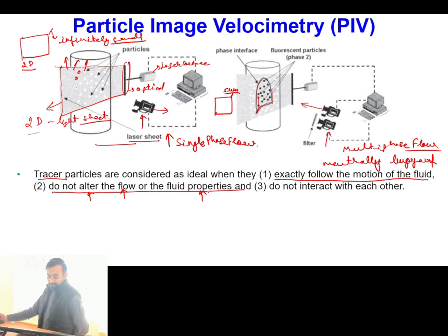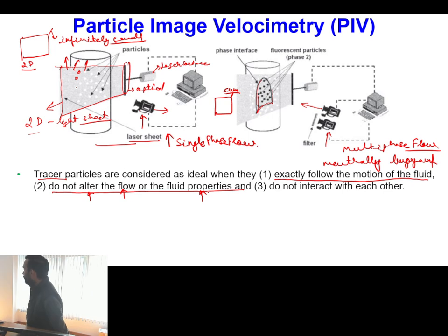So whenever we use particles, we have to keep in mind that particle concentration should not be excessively high, so that the density of the reference fluid is changing, or particle-particle interactions are becoming so high that the viscous effects are changing for the overall picture.